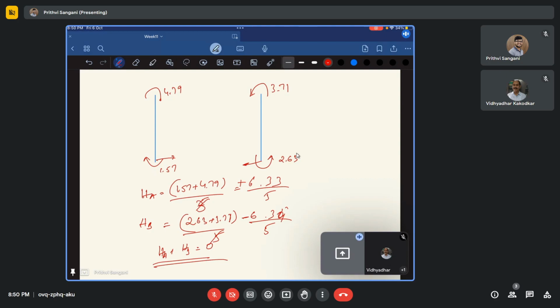The reason is that we are first calculating the net force for equilibrium in the horizontal direction, and then doing it in the vertical, and then we are finding out the sway, and from the sway we are finding out the net force because of that sway, and then we are proportionately dividing, sharing it with the initial values. So any doubts or any clarifications in this?